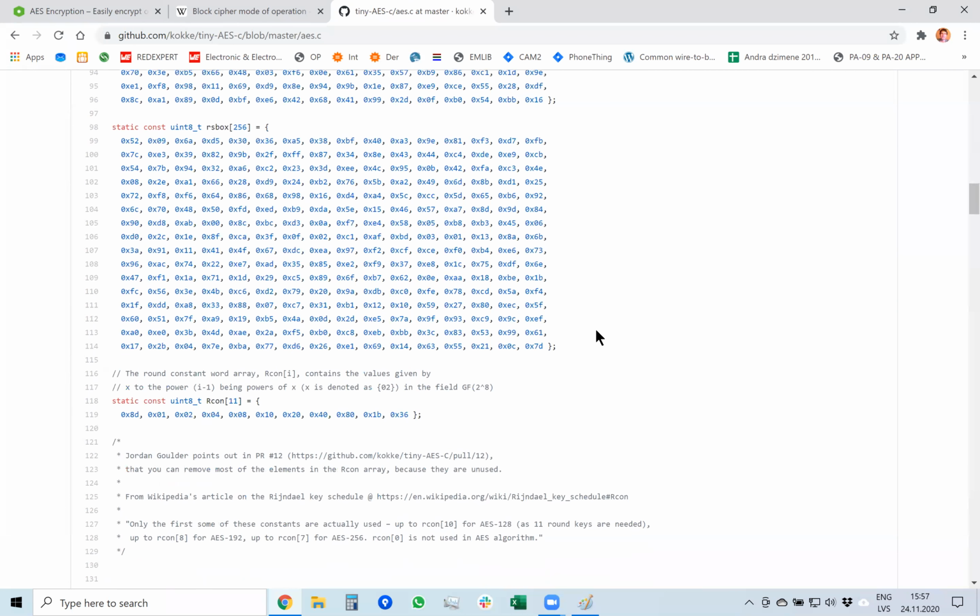Shifting rows and mixing columns can be done by simply rerouting the wires to the next part of flip-flops and so on. So this can easily be implemented in hardware. As a result, many companies sell microcontrollers that have an Advanced Encryption Standard engine built in.